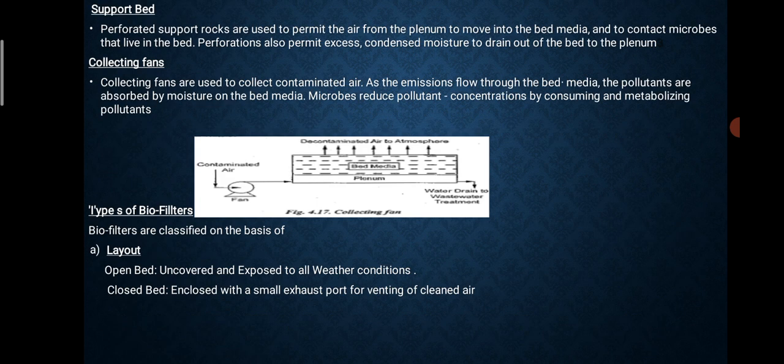2. Support bed. Perforated support rocks are used to permit the air from the plenum to move into the bed media and to contact microbes that live in the bed. Perforations also permit excess condensed moisture to drain out of the bed to plenum.